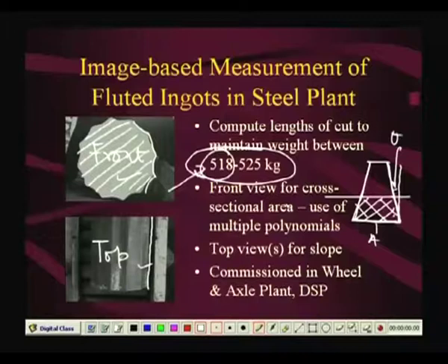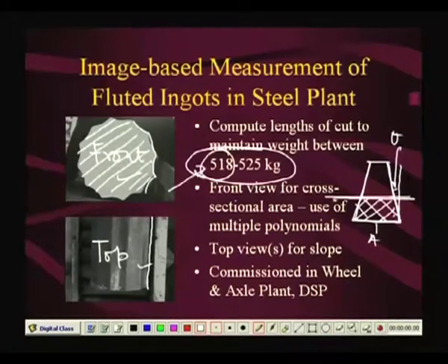So, you see this is an estimation where we are measuring the volume of the ingot. Now, is the volume of the ingot measurable by any easy way? No, not at all. If you really wanted to measure the volume, you can have a detailed mechanical measurement scheme, which is going to take much more time. So, here we had a scheme which is very simple. Just place the ingot on a roller, take 2 pictures, and immediately within seconds the estimation algorithm can tell you what should be the cut length here, such that this volume will be a given volume. So, this is our first example.